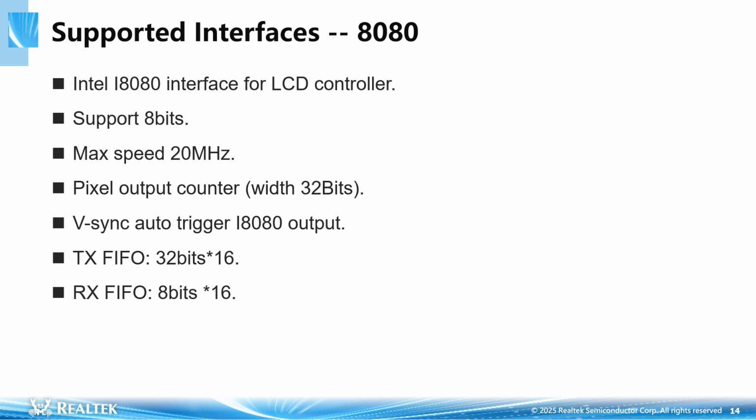Intel i8080 interface for LCD controller. Support 8 bits. Max speed 20 MHz, pixel output counter, width 32 bits. VSync auto trigger i8080 output. The size of TX FIFO is 32 bits multiplied by 16. The size of RX FIFO is 8 bits multiplied by 16.